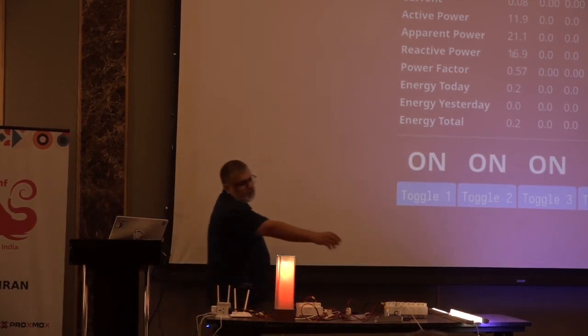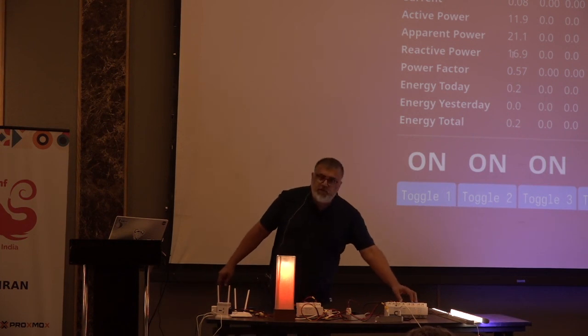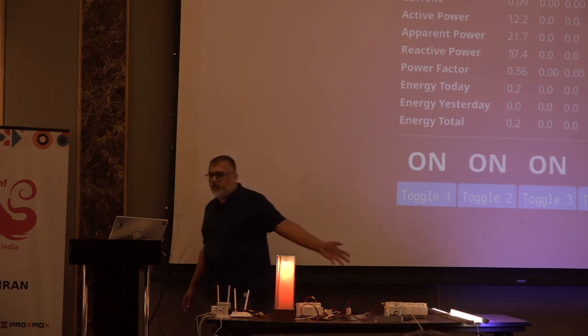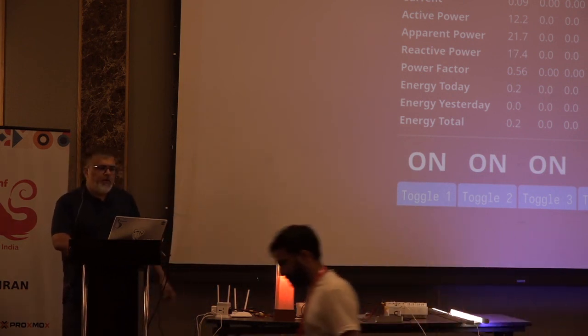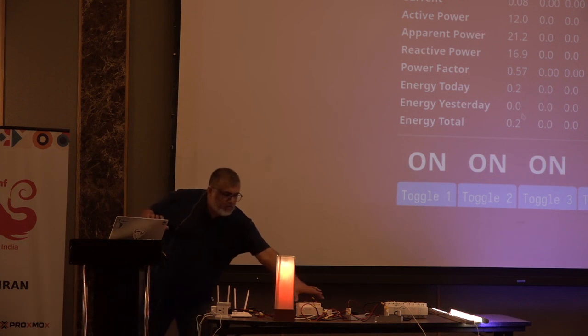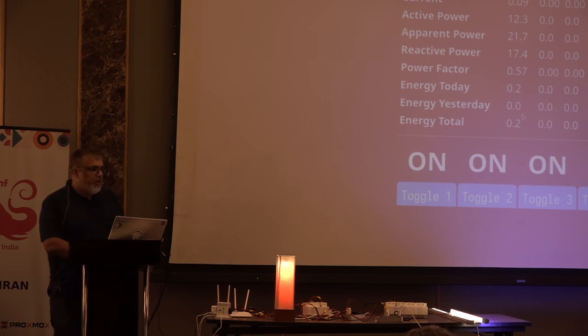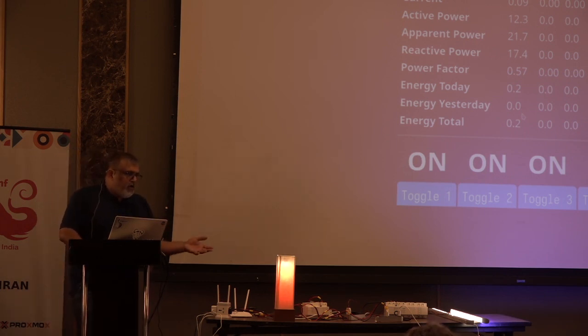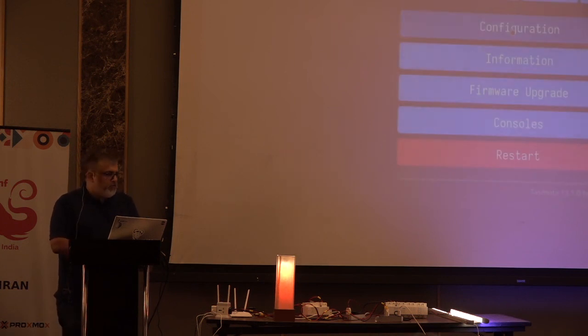All we have is current sensors which measure power consumption, how much current is being drawn and what the voltage is, and then we can compute the power factor and so on. This is the controller for that. Like I said, you can daisy chain many of those, and as a protocol, Modbus is very reliable. It's very popular in industries when you have to talk to various machines, right? So this is the thing.